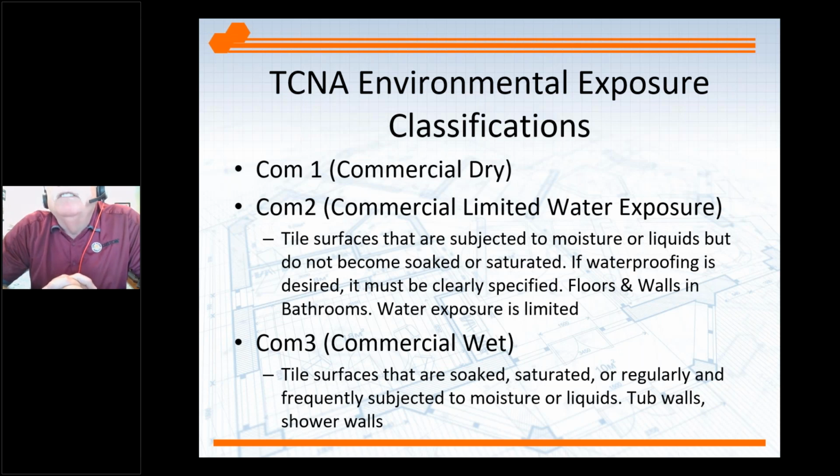So he installs the tile right over the gyp board with a mastic. This mastic was a water soluble mastic. What he didn't know was that the maintenance facilities or the janitors were coming in weekly and steam cleaning these bathrooms. They actually put so much water that they were blowing the tile off the wall.